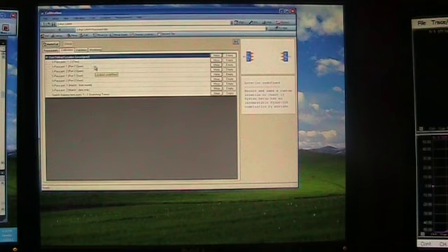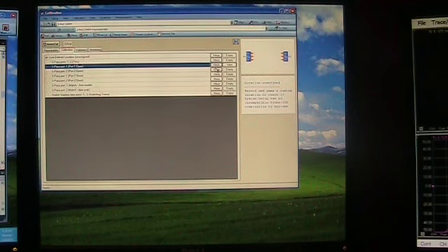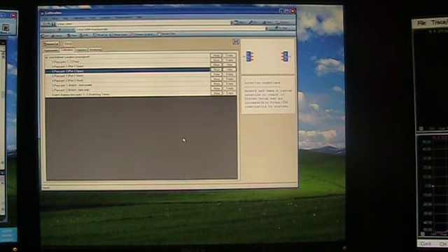So we're going to go ahead and just step through the standards here. I'm already touching the open standards that are on the wafers, so we'll go ahead and get those measured. I'm not going to move the screen over. I'm watching the network analyzer on the other screen. I have a state file running there that runs from 500 megahertz to 50 gigahertz in 100 megahertz steps. This not only will allow us to get the calibration that we need to create de-embed files, but it will also allow us to take scattering parameters of the device once it's under test.